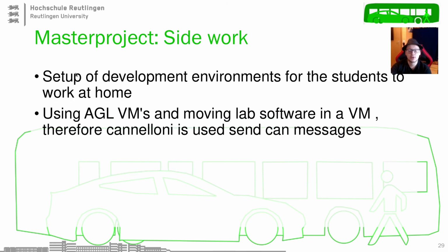So that students can work at the moment at home, I'm doing some side work and setting up the development environments for the students to work at home. We will do that with AGL VMs and our lab software, PySim, TUCAN and so on, in a second VM. To communicate between our software and AGL, we will use Cannelloni to send the CAN data from AGL to our software and backwards. So we can drive the driving simulator, generate CAN messages, send them to AGL, and get the values in AGL to control the applications with that.